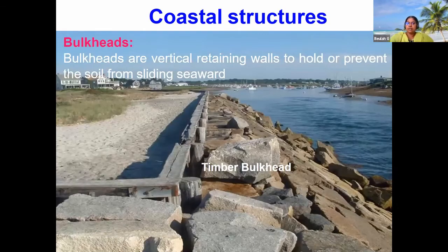Coming to the bulkheads. Revetments and bulkheads are typically formed coastal structures in any part of the world. You can see different sorts of bulkheads used universally. In the olden style, bulkheads were created using timber members. Nowadays we don't use timber bulkheads because their durability is quite low. To make sure they last 20 to 30 or 40 years, we don't recommend timber bulkheads. These bulkheads are vertical retaining walls to hold and prevent the soil from sliding seawards.